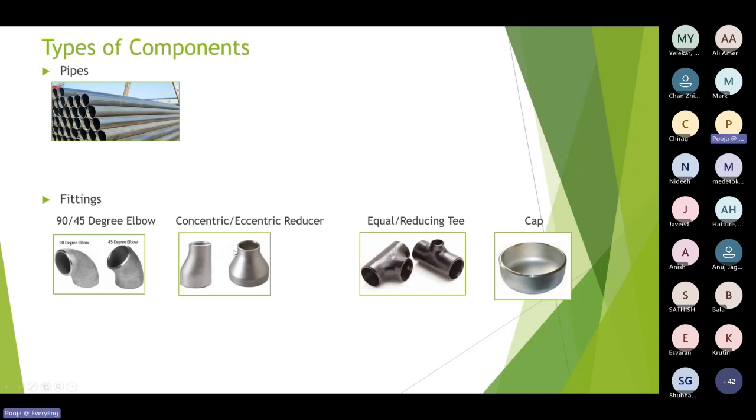For people who are not working in the piping industry, the example could be a pipe which is coming into your apartment. There is a water tank on the terrace of your apartment. From the terrace, there is one pipe which distributes the water to each apartment floor-wise. If you see carefully, for the first few top floors, the pipe diameter is big. Then the pipe diameter gets reduced step by step. And how is that reduced? By connecting the reducers. Now, where to use concentric and where to use eccentric, that's another part.